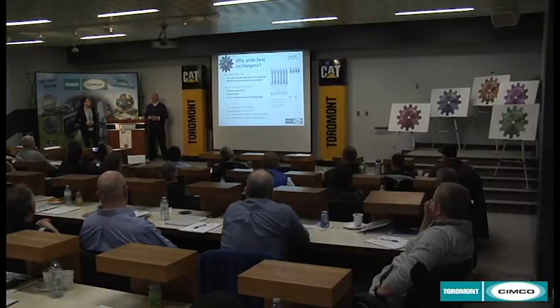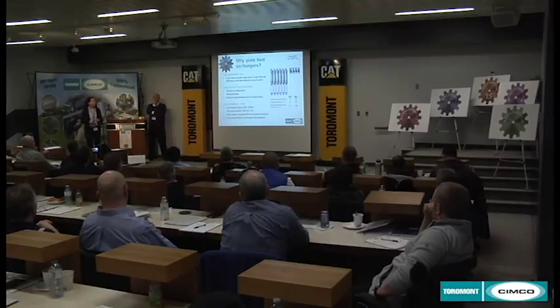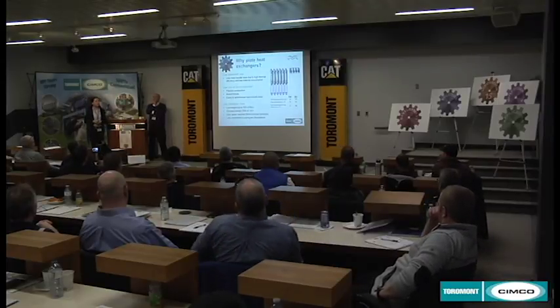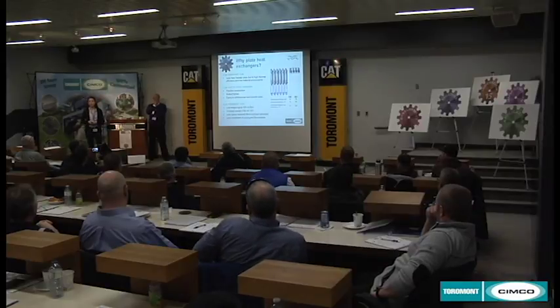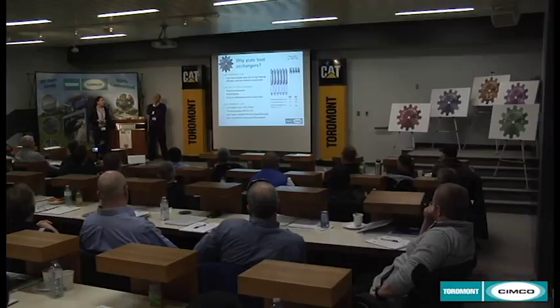So the question is, why plate heat exchangers? First of all, it's a low investment cost. We have less heat transfer area due to high thermal efficiency and low material consumption. It's a low-cost future for expansion. You can add or remove plates as soon as you have a bigger load. We have as well flexible construction and bolted frames.